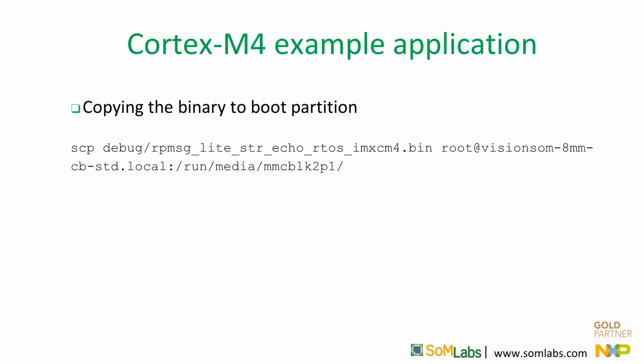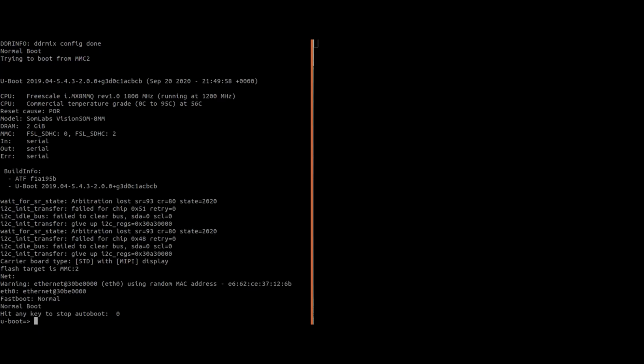Before starting, you can also connect the UART USB converter to the UART3 port, as in the previous section, while modifying the device tree for UART3. It will display the messages sent by the Cortex-M4 application, but this step is not necessary. Let's connect to the serial terminal, the J-Link console socket, using a micro USB cable. Next, let's reset the device so that we can see the U-Boot logs in the terminal.